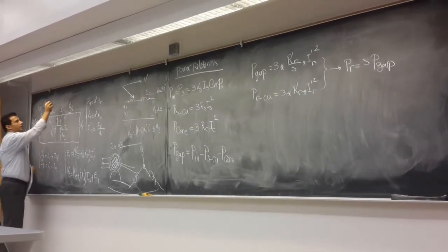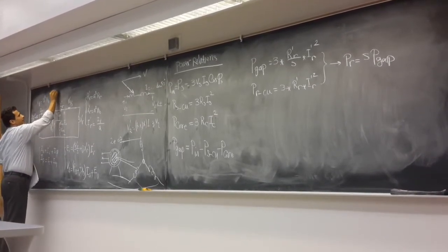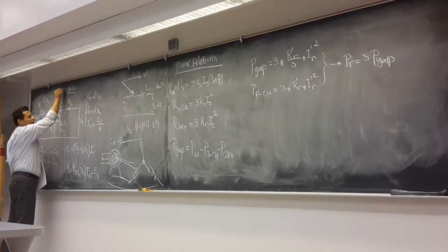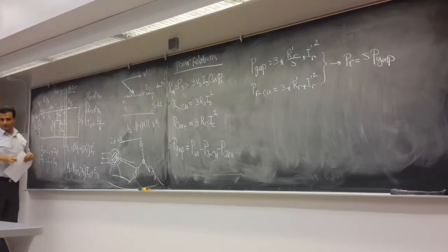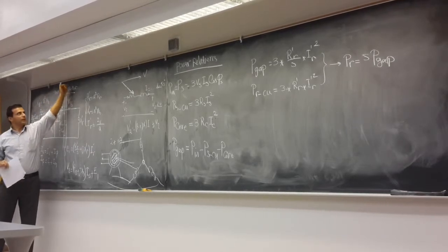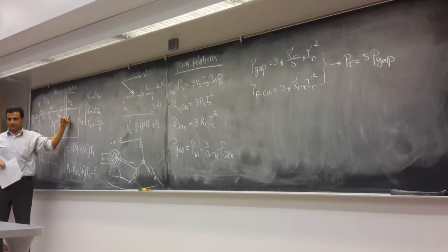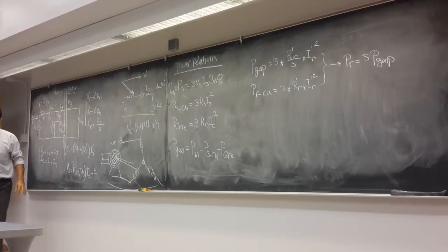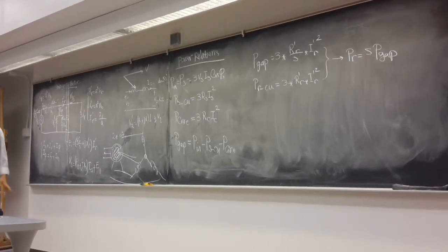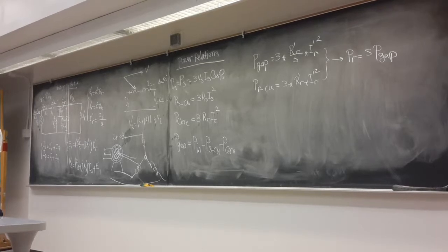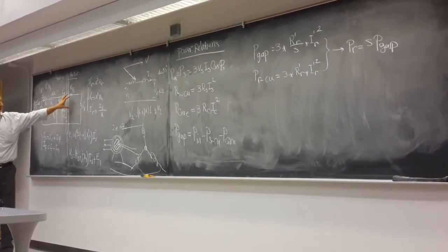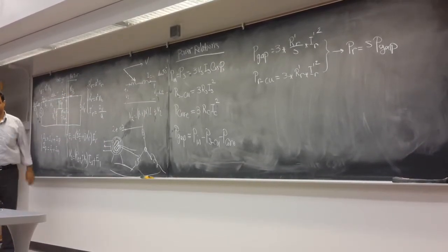This side is a stator, right? From here is the rotor, right? And between a stator and rotor there is an air gap, right? I call it gap. The power coming from here is going to be dissipated here, right? But in the rotor, how much power loss do you have in the winding of rotor? If the resistance of the winding is R, it's going to be R I squared, right? We have three of them, 3 times R times I squared. But I'm going to develop this circuit a little bit more. Give me a little bit more time.